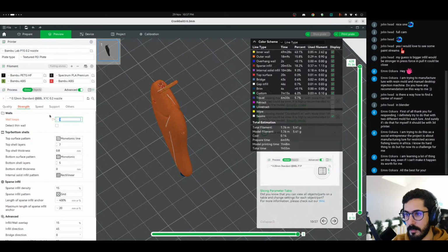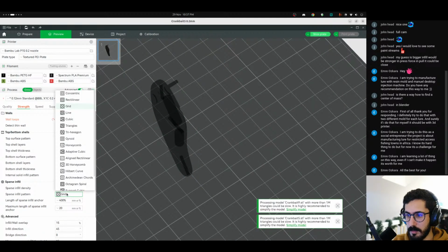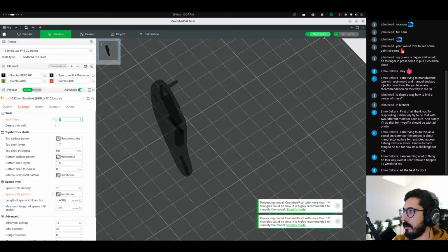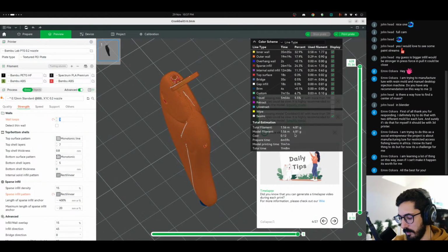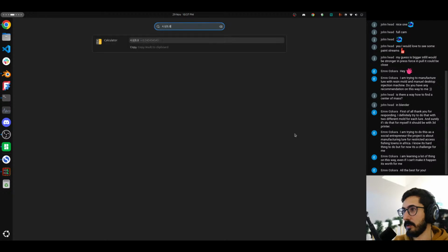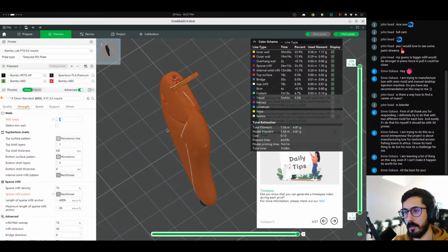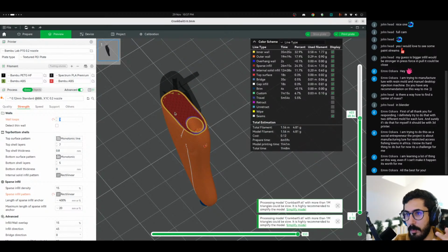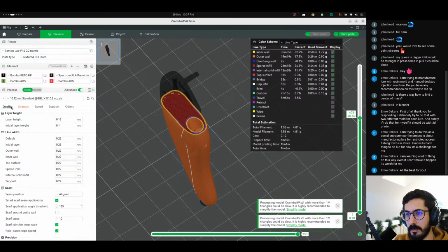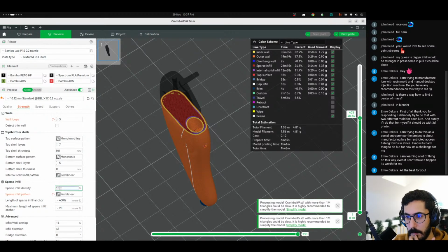5.4 still. Okay, so 3. This is gonna be, let's say, rectilinear. 4.8 divided by 8.8. Still too much, because I want this to be a slow sinker. Like, wow. We're using 3 walls on a 0.2 nozzle. That's insane. Need to reduce it even more.